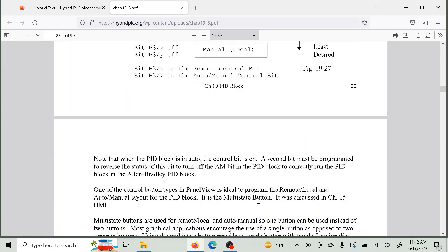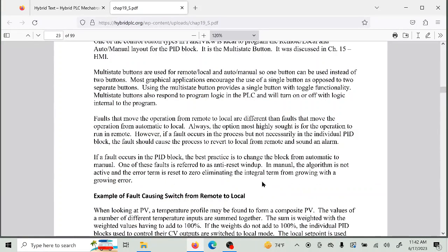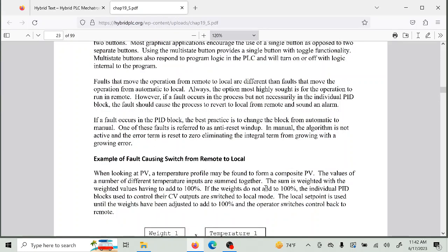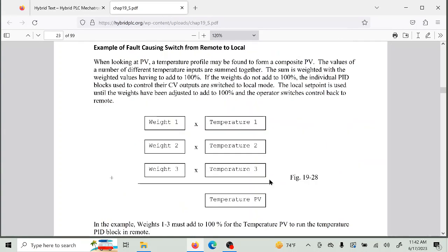Now here's one of the things that they did. Let me go back. Okay, so in the input to the temperature controller, you had one input, but they wanted to hedge their bets. So basically they had a number. I think they really had 5, but I just showed 3 here. But 3 thermocouples coming in. So we'd have thermocouple 1, thermocouple 2, thermocouple 3. And they wanted to do an average of those 3.